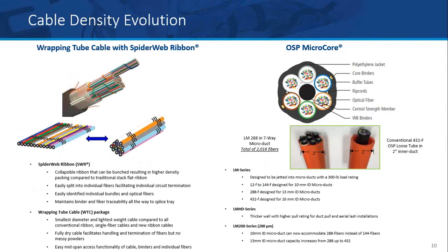And what this does, since those fibers do collapse down rather than maintaining a rigid, straight organization, that collapsible structure allows us to fill all the interstitial spaces inside of a ribbon cable. So what that means, we cut out all those interstitials. An equivalent 432 fiber cable, for instance, compared to a 432 fiber rigid ribbon structure has reduced the diameter significantly. We've seen cases, when you do a comparative, of up to 50%, just depending on the fiber count. And with that comes a lot of advantages.